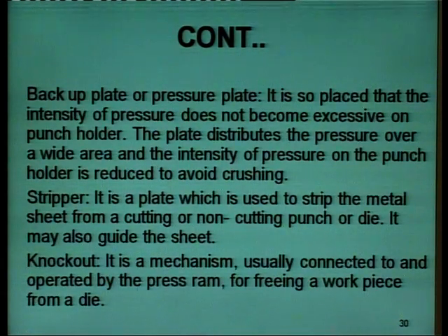Now, the backup plate, or we can say pressure plate, is so placed that the intensity of pressure does not become excessive on the punch holder. The function of the backup plate is to distribute the pressure equally over a wide area, so that it does not become excessive on the punch holder or break the punch. Just to avoid breaking or crushing of the punch, a backup plate or pressure plate is used.